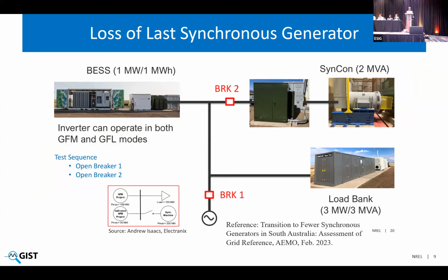It has an inverter, a battery energy storage system with a 2.2 MVA inverter, which can operate in both grid forming and grid following mode. It has one synchronous condenser, which can also be operated as a synchronous machine, and a 3 megawatt load bank. All these are real devices, and the grid symbol that you see over there is actually from a grid simulator.